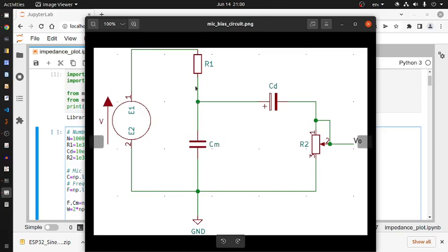From this connection we take the signal out, and it passes through an electrolytic capacitor and goes through a resistance to ground. This resistance we can also vary to control the output voltage. Instead of calling it gain, I should say the output voltage.